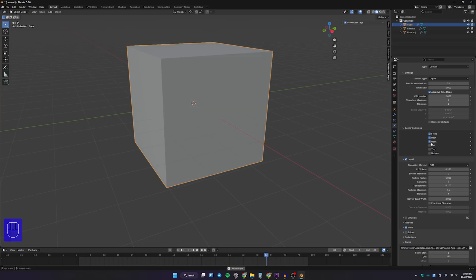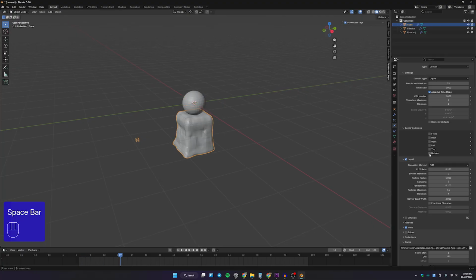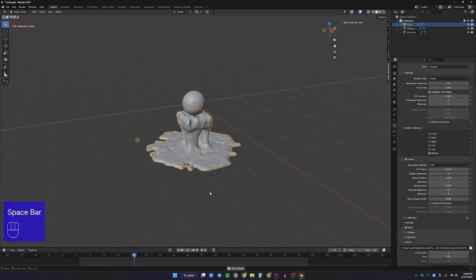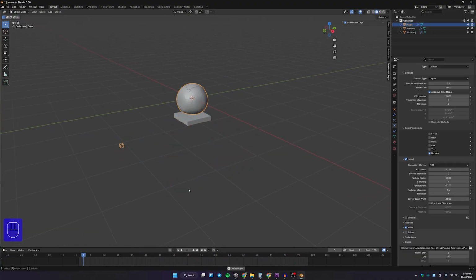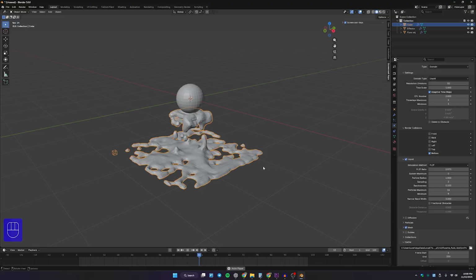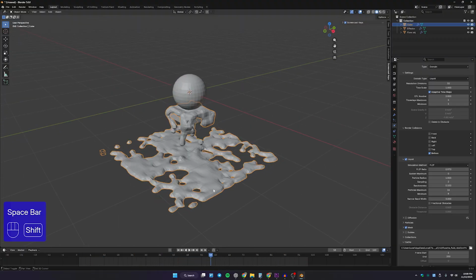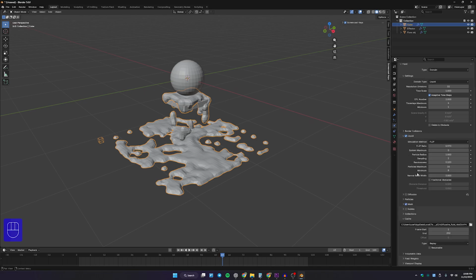So you can do this for all these faces, and right now we have no collisions with the side faces. So let me turn on my bottom face again, and if I do like this, I can see my side faces are hidden, and then the flow is no longer colliding with these faces, and it just disappears like this. So for the rest of the tutorial, I'll keep these settings like this, and I'm going to collapse that, and then we can come over here into the liquid section.